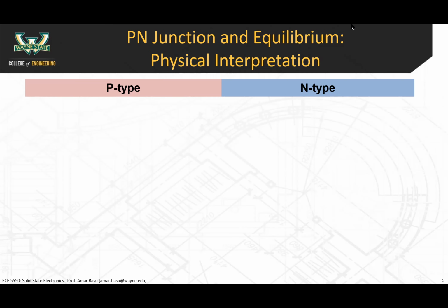For me, the first that comes to mind is diffusion. Okay, so why would diffusion happen? So in the n-type material, right at the interface, you would not have many holes, and in the p-type, you wouldn't have many electrons. So you would get a crisscross type of situation where the electrons will diffuse to the p-type, and the holes will diffuse to the n-type.